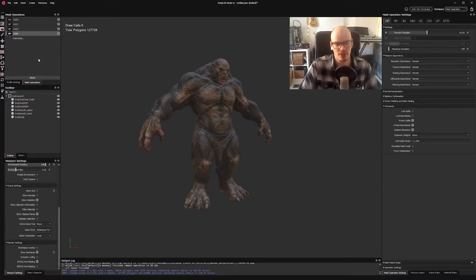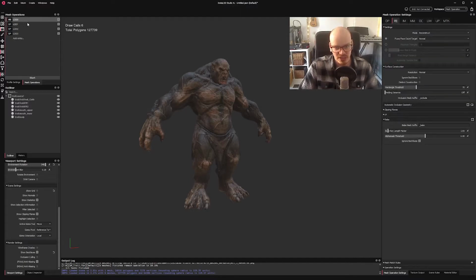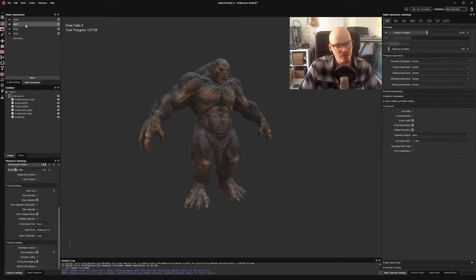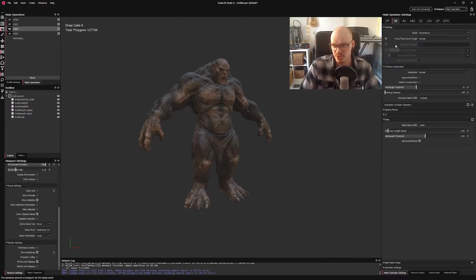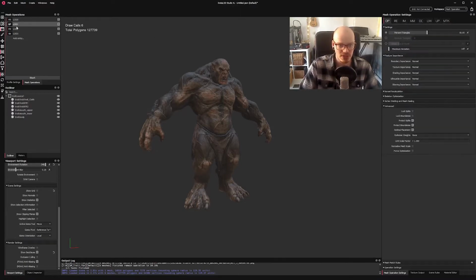We could go on and on and on with whatever settings you want. Now, for every entry, we can change the feature and all of the settings, which is really powerful. So this gives me a huge amount of flexibility and control. For example, if I wanted to, I could have LOD3 be a billboard imposter. We could remesh LOD2 to maybe 5,000 polygons, and then we could simply optimize LOD1 to 50%, right? We've got all of that control if we need it.